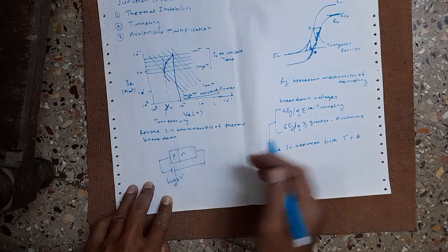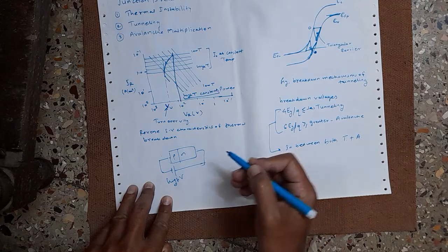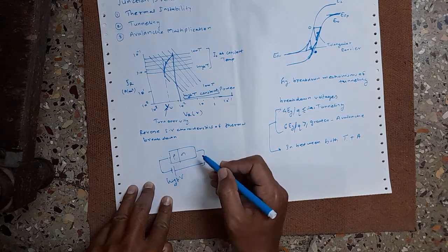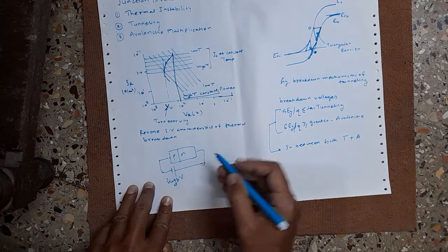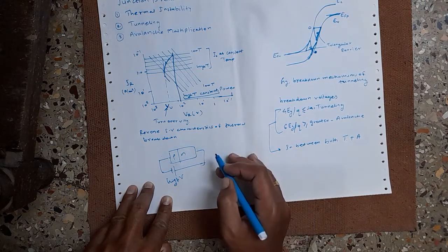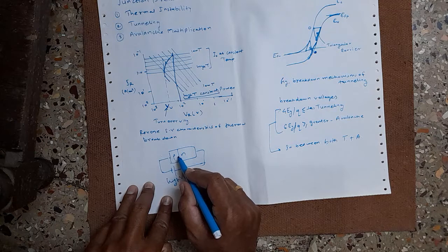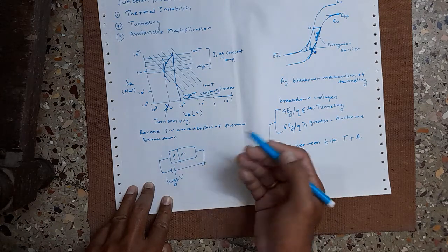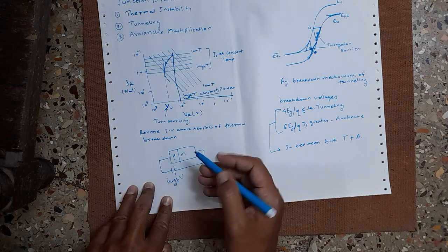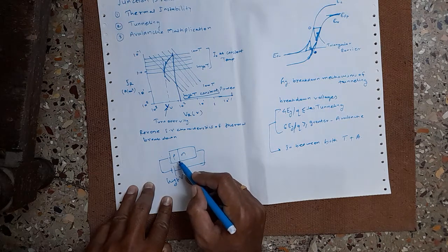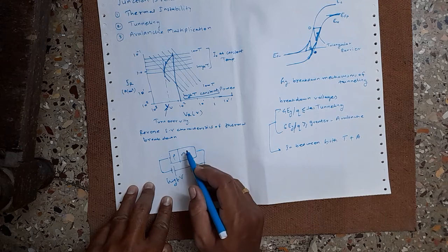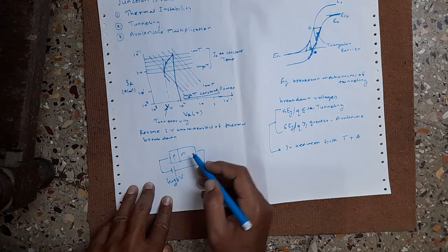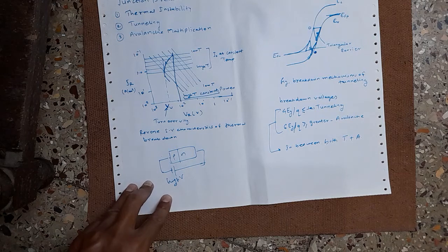This temperature increase in turn increases the reverse current in comparison with its value at low voltages. This is something like positive feedback, because thermal motion increases the current in the reverse direction, and this is responsible for the breakdown of the PN junction.